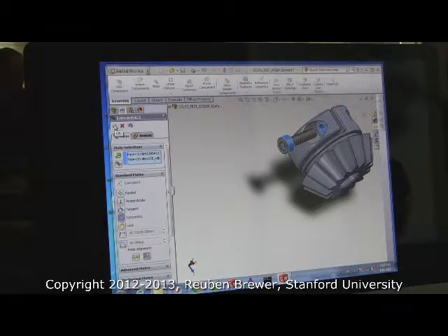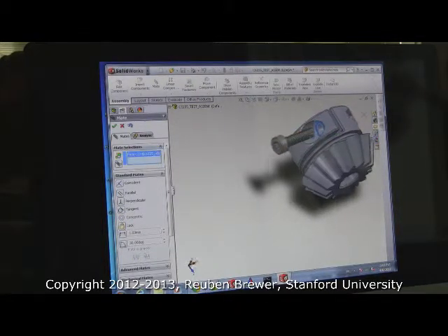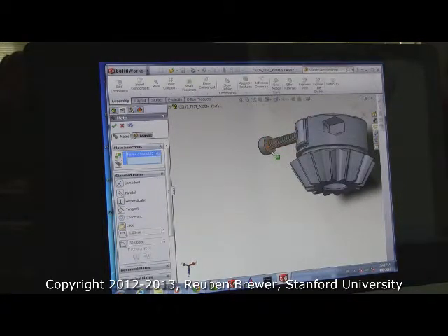If I kept it concentric where it was, and then on the next step I tried to touch the surfaces, I get an error saying that concentric won. So I should go back and just do it on the concentric and not on the second step. Yeah, it's a step after that. Select this, and then select this.